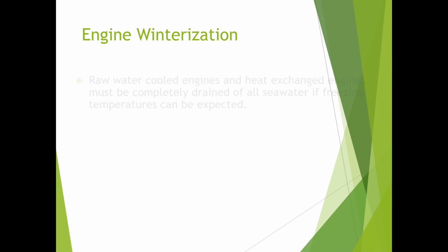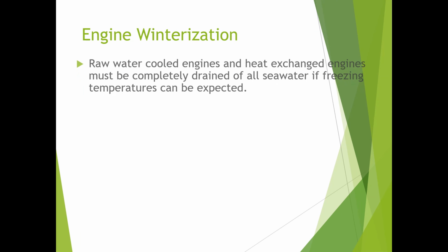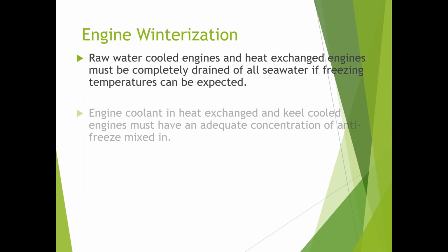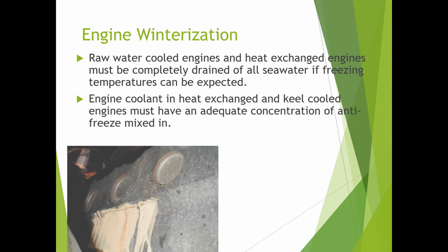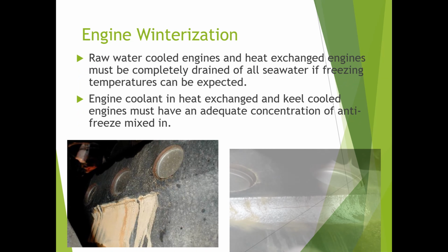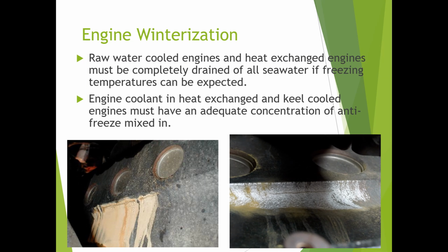Engine winterization. Raw water cooled engines and heat exchanger engines must be completely drained of all seawater if freezing temperatures can be expected. Engine coolant in heat exchanger and keel cooled engines must have an adequate concentration of antifreeze mixed in.